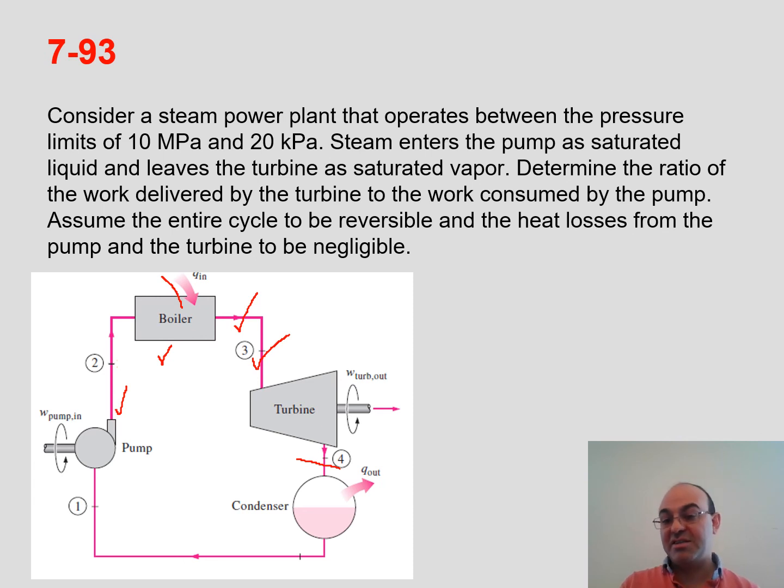at superheated steam. Then at the inlet of the turbine, the superheated steam expands, generates work, and the work is given to the generator. Then at the exit of the turbine, the steam exits the turbine, usually in the saturated state, a mixture of a little bit of moisture and vapor. It's very close to saturated vapor at x equal to 1.